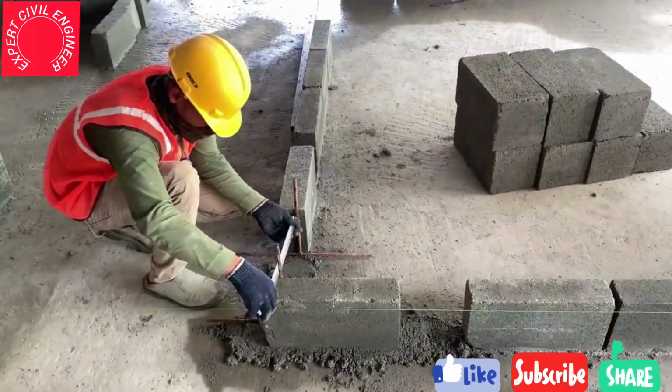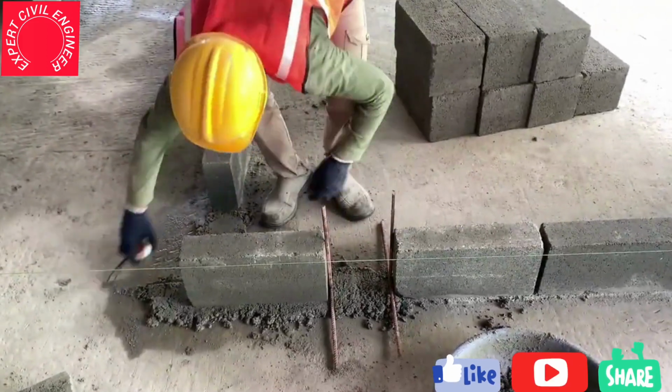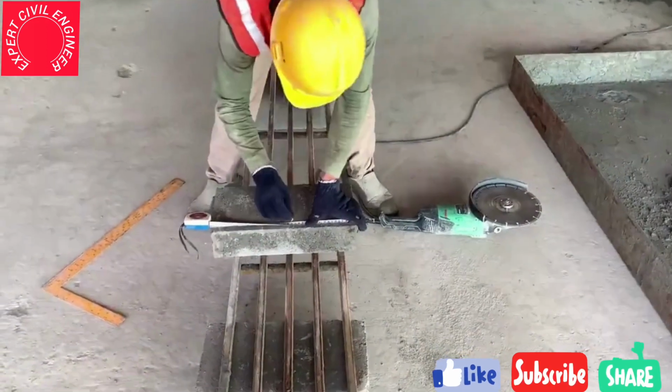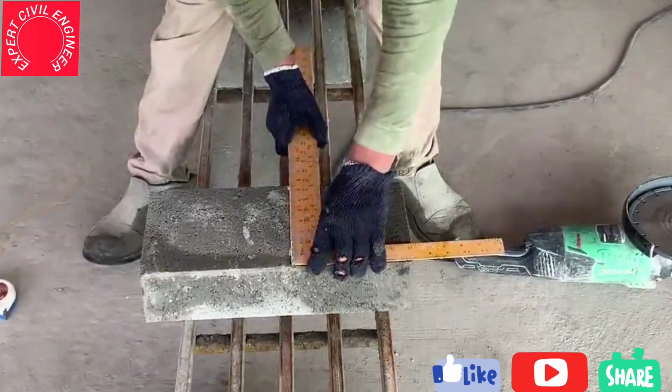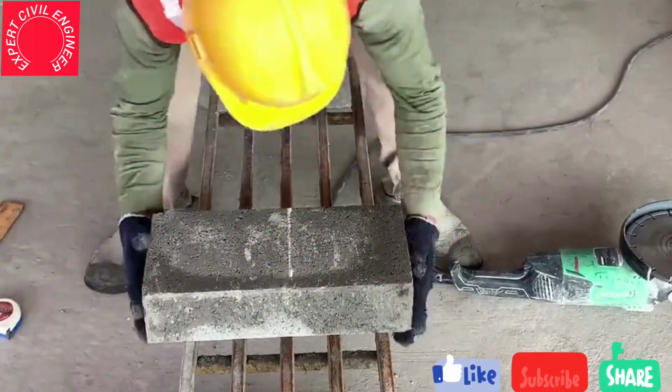At the corner, if the block size is smaller than a full block, measurements should be taken, and the block should be cut to the required dimensions and proper shape by using a handheld block cutting machine or table-mounted block cutting machine. A joint gap of 12 mm on both sides to be considered while taking the measurement between the blocks.